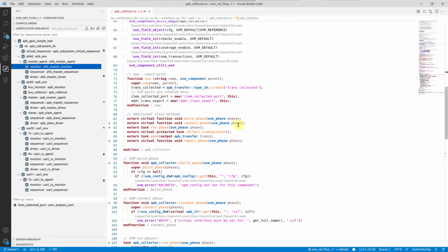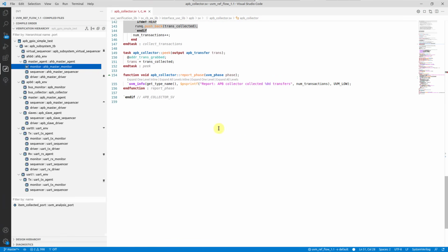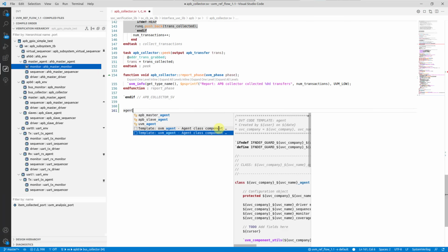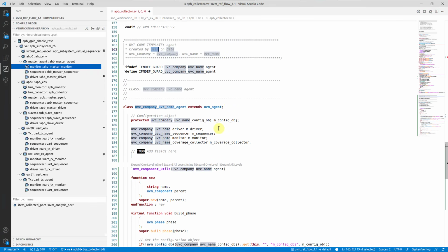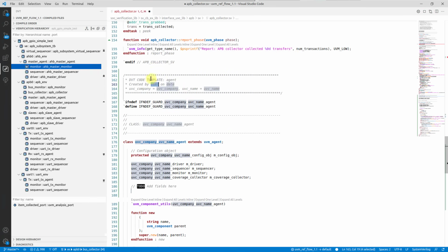Furthermore, you can quickly deploy code templates, snippets of code ranging from a simple for loop to entire test bench components. In order to get template proposals, you need to type in a prefix prior to invoking Content Assist using Ctrl space. Press Enter to choose a proposal, then fill in the customizable parts of the code snippet, which are called placeholders and enclosed in colored boxes. Press Tab to move to the next box, or Shift-Tab to go to the previous one.